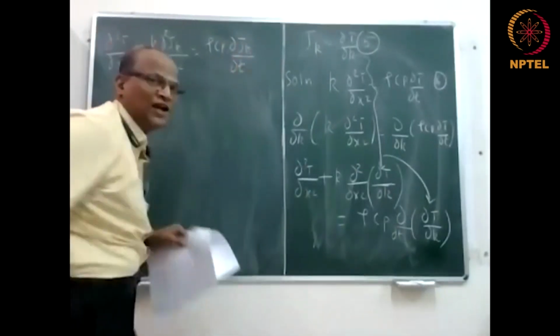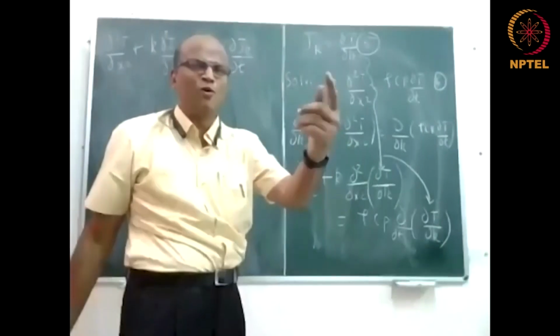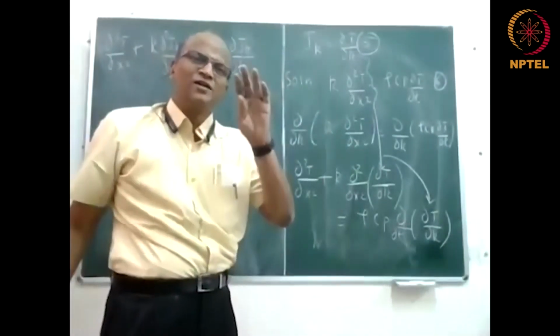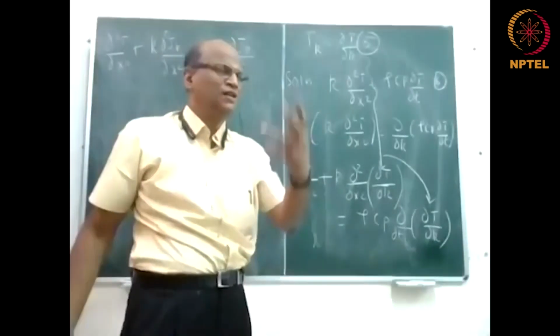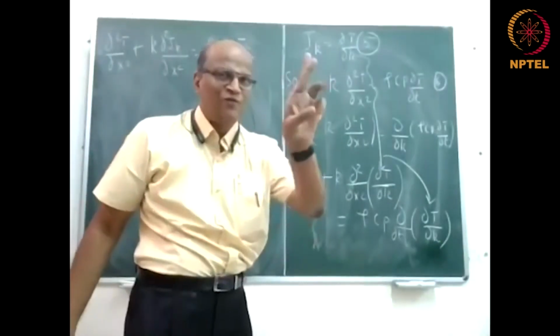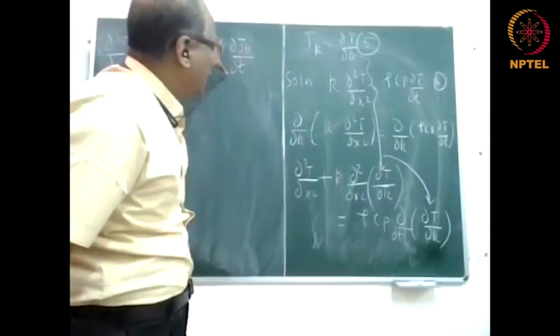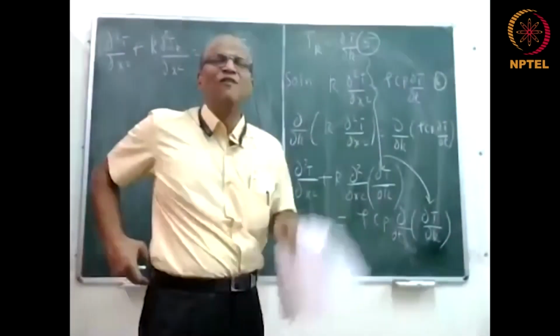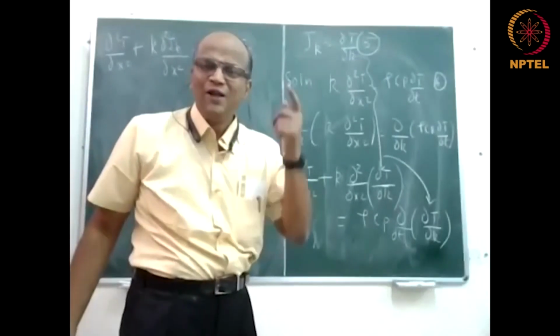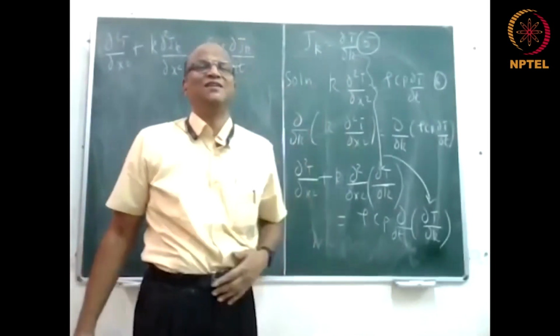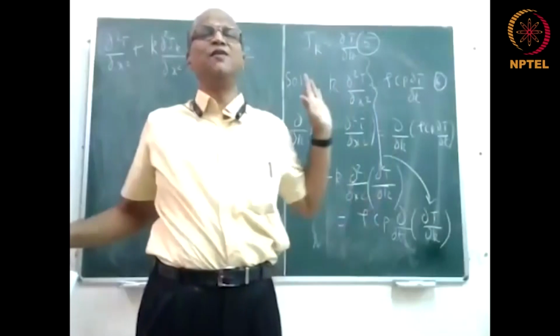Please note that quietly we change the problem into a problem in J. So we are formulating the problem, not for T now. We are formulating for J. And now you will have a different differential equation with initial and boundary conditions. If you solve it, you will not get the temperature, you will get the J. Okay. So this is the sensitivity problem.